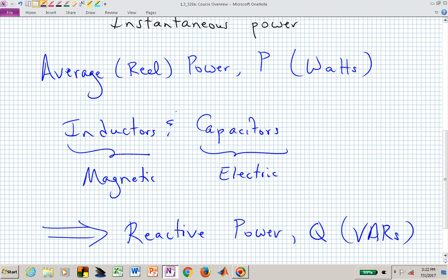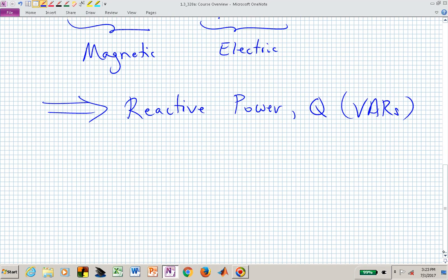that's helping us to drive machines or to move equipment, etc., that the power company wants to deliver to us. But because we have these inductive systems, maybe a bunch of big machines, we may want to introduce some capacitor banks to counter the effect of the magnetic fields. We may want the electric fields and the magnetic fields to be helping each other out on our load side. And so we are interested in, and so is the power company, this combination of real power and reactive power.